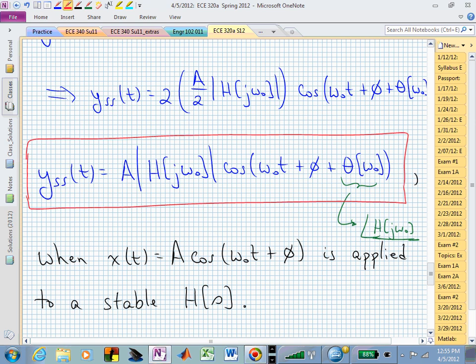You do that by looking at the imaginary axis and asking what the poles and zeros and the gain of my transfer function, capital H of S, do at this particular frequency, omega naught, determined by the frequency that we were exciting the system with, x of t.